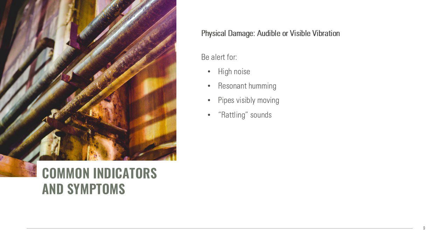Physical damage number 4, audible or visible vibration. Human senses, sight, sound, and touch, often detect issues before instruments do. Operators' observations are valuable inputs. Be alert for high noise, resonant humming, pipes visibly moving, rattling sounds.